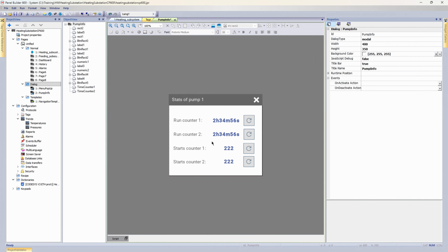There is another problem, not related to the widget though. Currently, dialog window only works for pump 1. By now, you've probably realized that I'm not exactly in the mood for copy-pasting today. So how do we keep only one dialog window and switch pump data dynamically? The answer lies in the feature called index tag set.